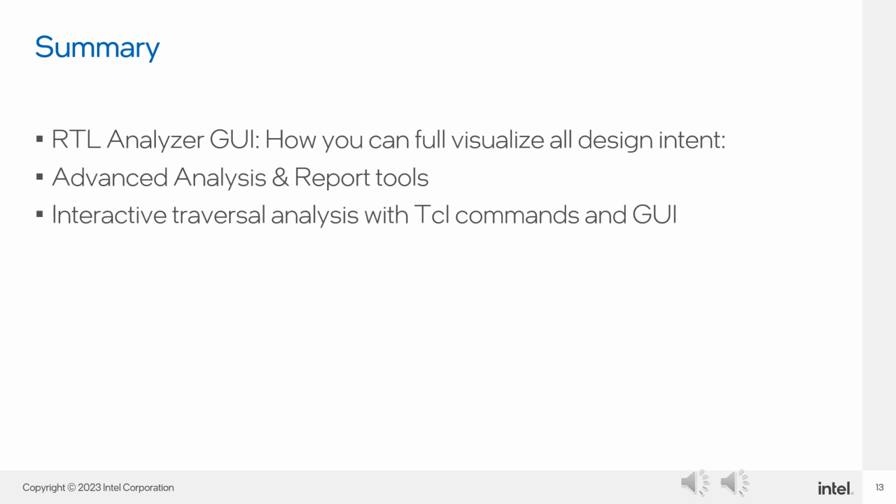In this video, we talked about the benefits of using this new feature. We learned about the different tools that the RTL Analyzer offers us for early design analysis, like Sweep Hints, Find Object, and finally, we had a small example of the interactive and traversal analysis with Tcl commands and GUI.